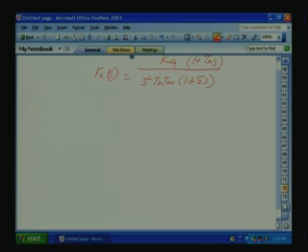Now if you see here, there is a 0 at 1 by Tn and a pole at 1 by delta. Now we want minus 20 dB per decade. So in F0(j omega), we place 1 by Tn here, and 1 by delta there.